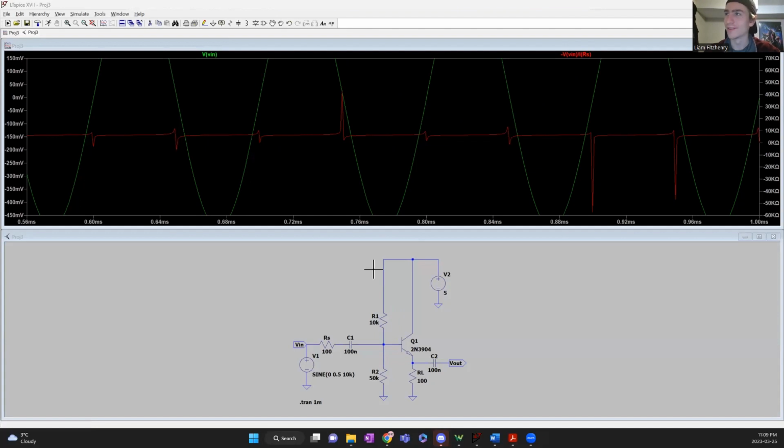Okay, sorry, one final thing that I want to touch on before we exit the simulation part of the project is determining the input resistance of our constructed amplifier. So simply to determine this, I plotted our input voltage from this node here, and I inserted a math channel on our plot here. That was the input voltage divided by this current, so the input current basically.